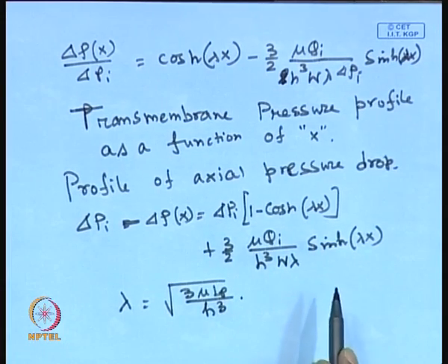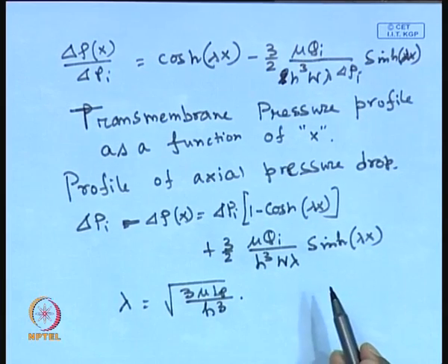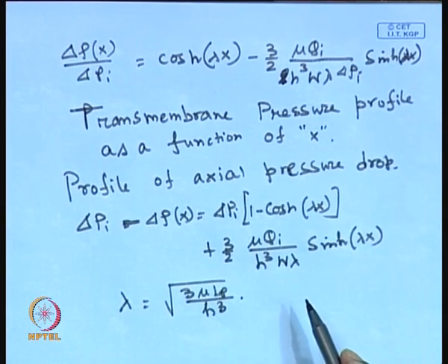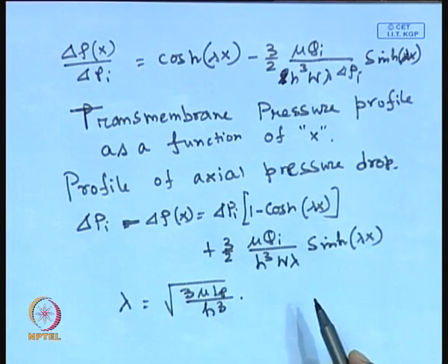In fact, if you have already done the other chemical engineering courses that I am talking about, in all the chemical engineering equipment, whenever you are talking about the flow through a tube or any column design, let us say packed bed or fluidized bed, this pressure drop calculation becomes very important. The idea is one has to calculate the pressure, because in a flowing system pressure has to decrease because of the friction and other fittings and other losses. So, you have to design a pump accordingly, so that you can overcome that much of pressure drop and can deliver at a desired flow rate.